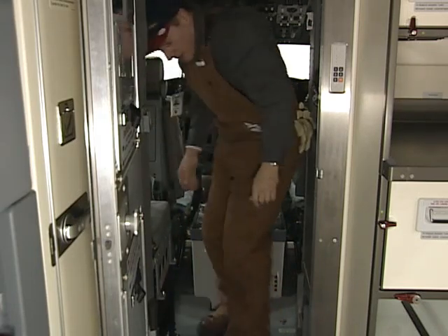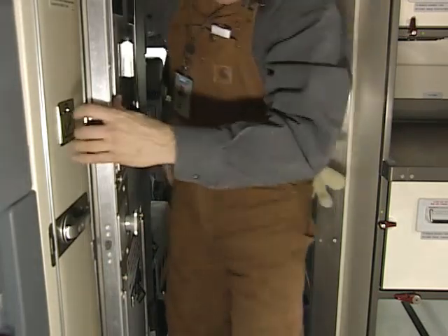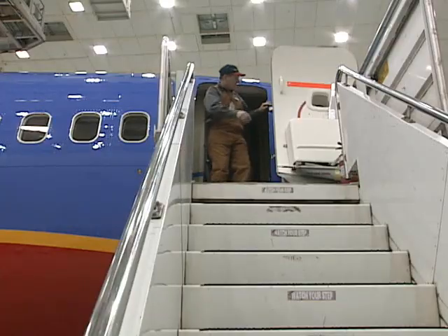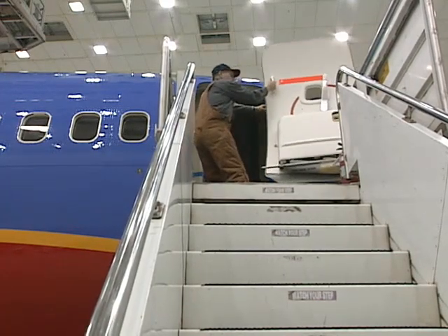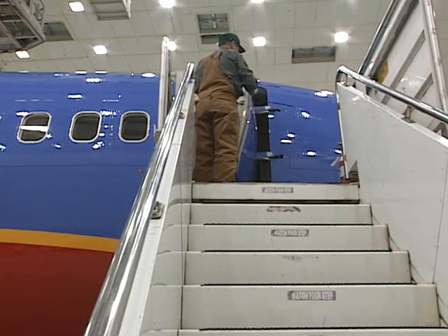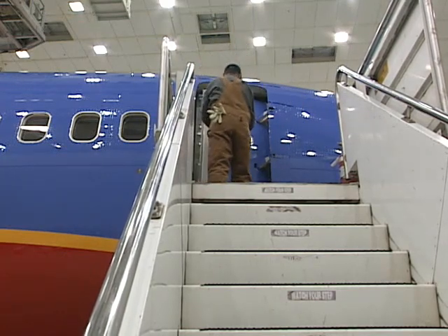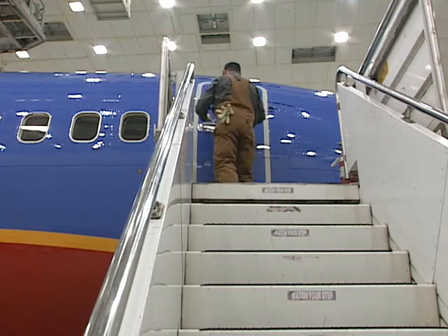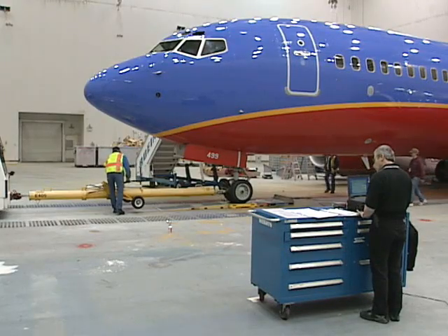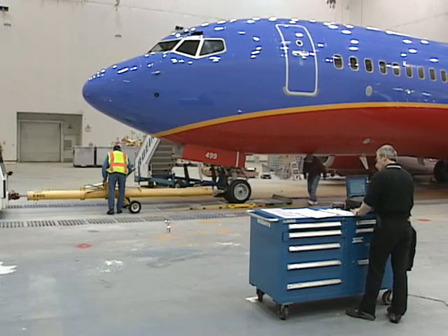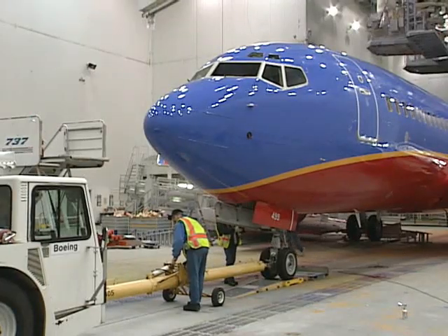Caution: do not use the airplane brakes to stop the airplane on the scales. This could damage the scales or induce side loads on the scales, resulting in erroneous readings. Make sure to close any open windows, move the captain's and first officer's seats fully forward, and close all doors as you leave the plane. Then disconnect the tow bar.